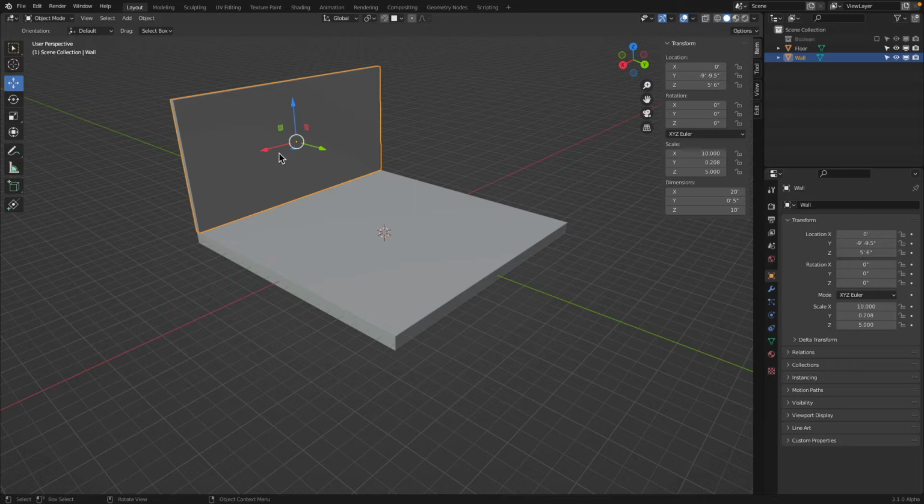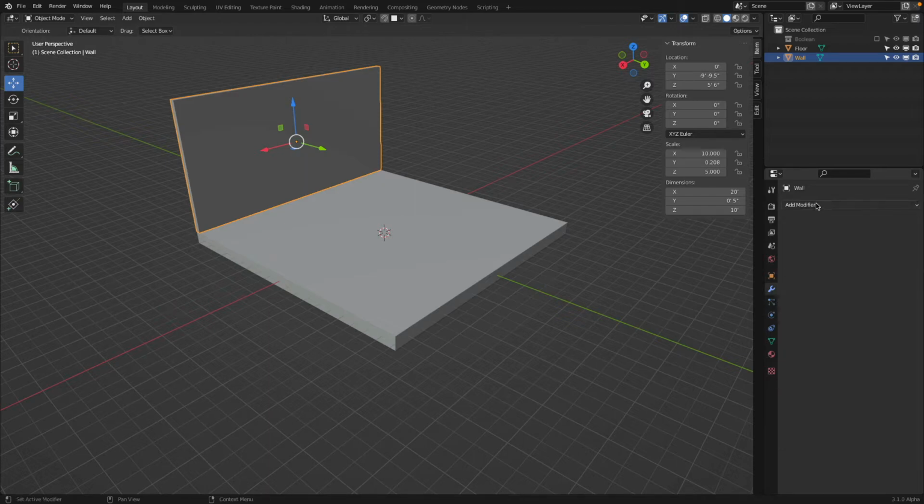So Blender is a modeling tool that allows you to interactively generate geometrical results. So we will tell the software, take this cube we created and remove it from this wall. So I need to add a function to this wall. These functions are called modifiers because I'm modifying that geometry.